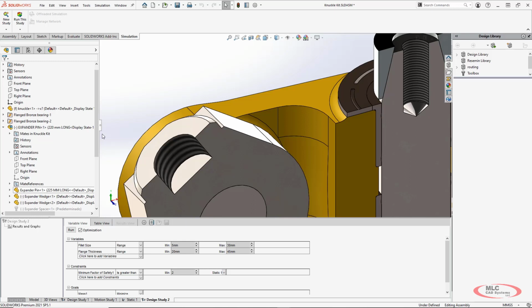see how effective they are and how comfortable people will be in different environments. It can be used to do airflow over objects to get drag coefficients, see how aerodynamic parts are. It can be used for water flow through pipes or valves. And with that, you can even export the forces that are acting on those pipes or valves back into SOLIDWORKS Simulation to analyze if they're going to break from those forces. So lots of different applications. But for SOLIDWORKS Flow Simulation, there's only one type of license. For simulation, you had your 3, but for flow, it's just the flow.